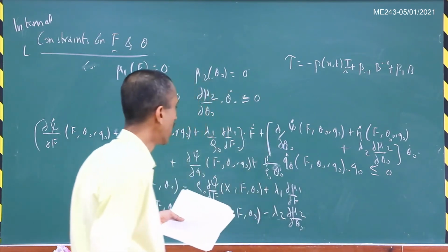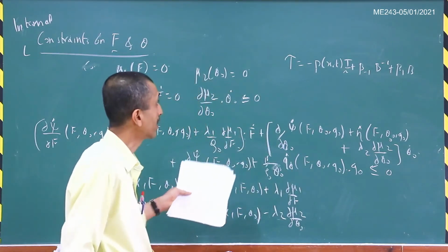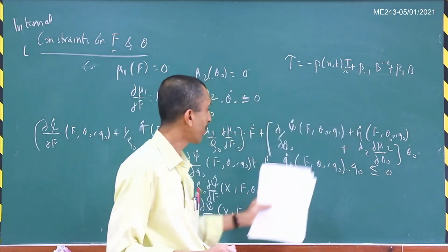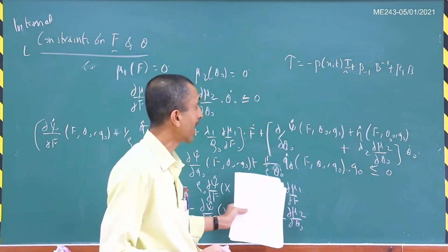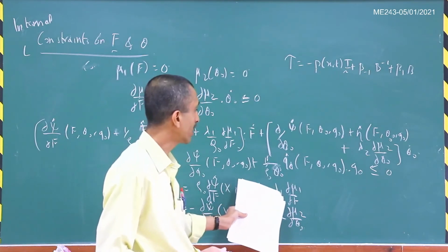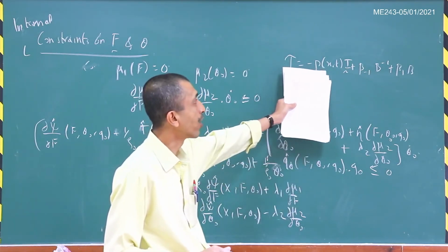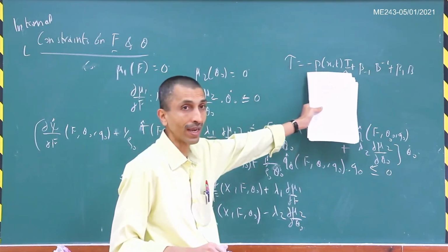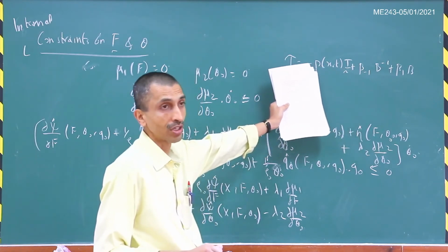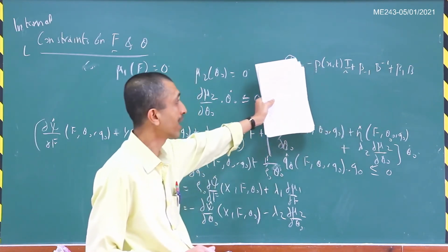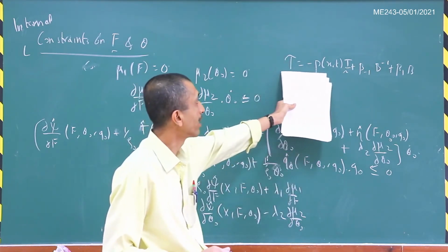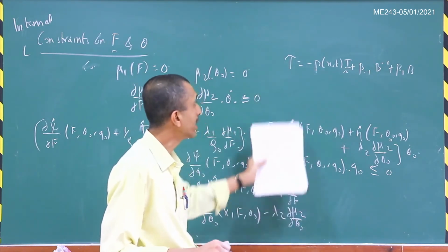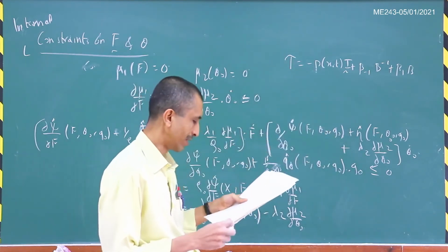And so now you can see that basically this indeterminate part is coming because of this particular term that is getting added. See, if the constraint had not been there, then we would have got beta naught of I, where beta naught would be a function of the principal invariants of B, correct? But now, because of this particular term, in the presence of incompressibility, you will get this particular term. So we will see that.